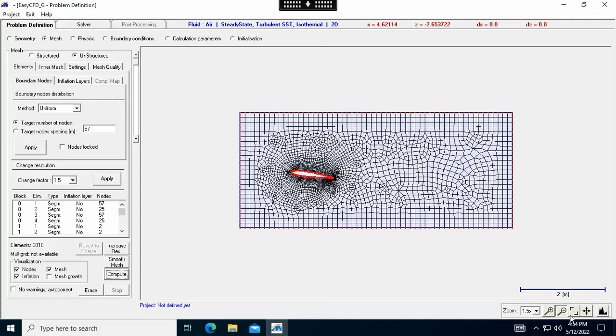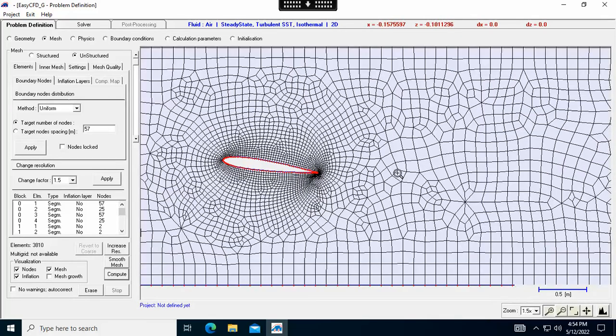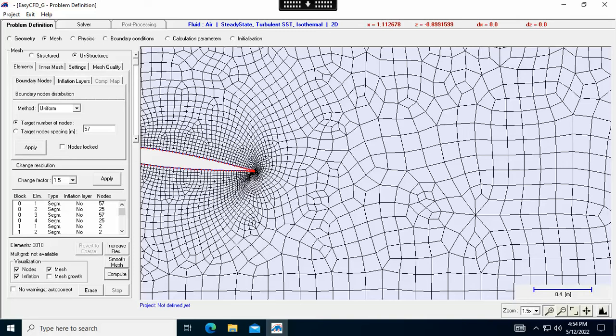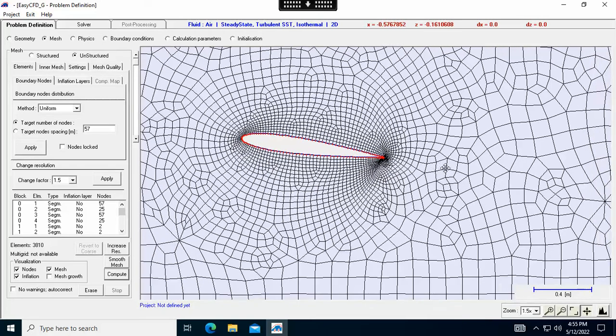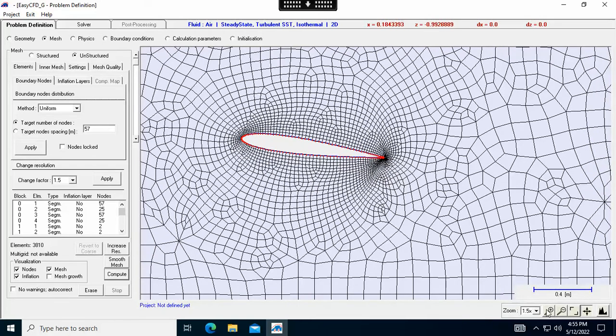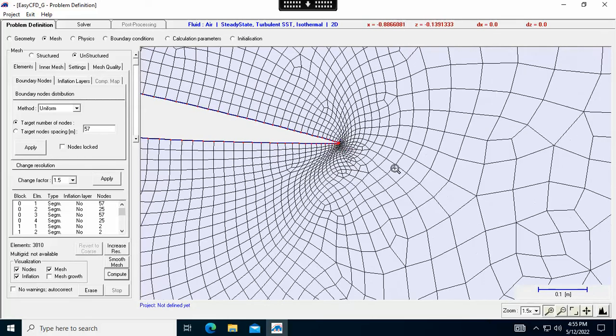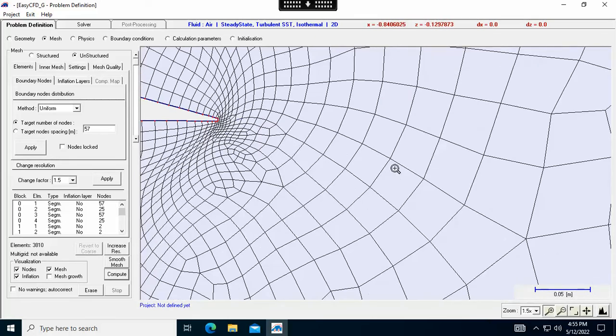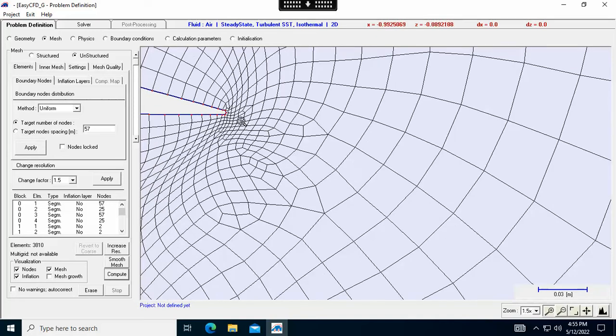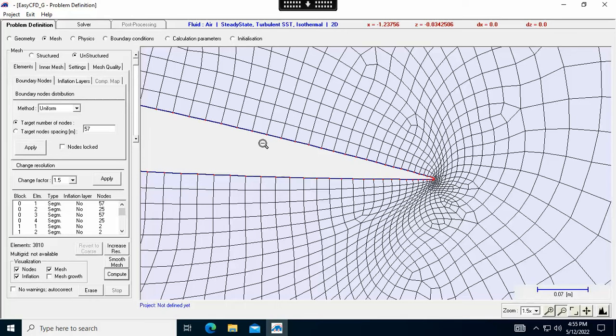That's nothing really. In a three-dimensional simulation, which this is not, you would have in the millions probably, at least a million cells. So there we go. You can look at it, and a good mesh is one where the cells are not too distorted from a rectangular or a square shape in this case, with this type of mesh. And let's zoom in, and here you can see, well, some of them look a little weird, but actually they don't look so bad. We can get away with this, I think. And I'm just going to zoom back out.